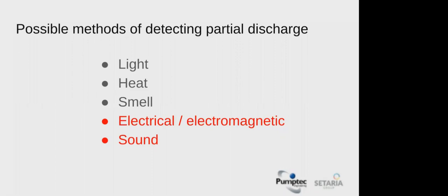They give off a little bit of heat, but that heat is very localized. It's very intense, but localized. And yes, if you can point your infrared camera directly at the source of the partial discharge, you will see it. But again, it's not much help for a typical indoor medium voltage switchgear because there isn't enough energy to heat up a complete panel. So you won't see one panel that's warmer than another one just because there's a partial discharge behind it.